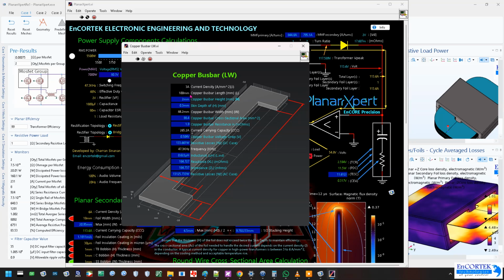So it depends on your current density you want to use over here, right? You pretty much could do that. So whatever current density that you want to do, I have some standard current density here, 3, 4, 5, 6, right? You could go up to 8 and things, but I just put some defaults here. So if you put 8 here and hit enter, you will get the 8 still, but when you scroll it with the standard, so either way you want to work with it, right?